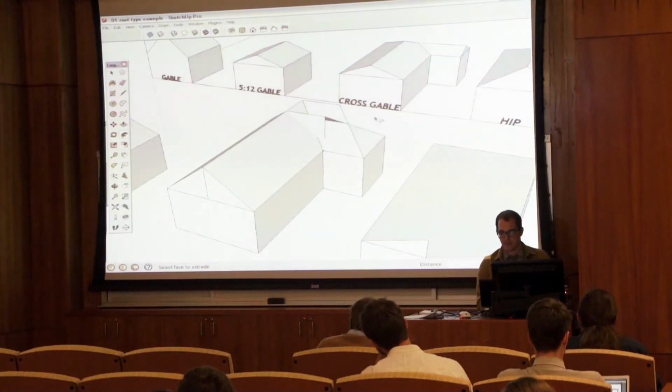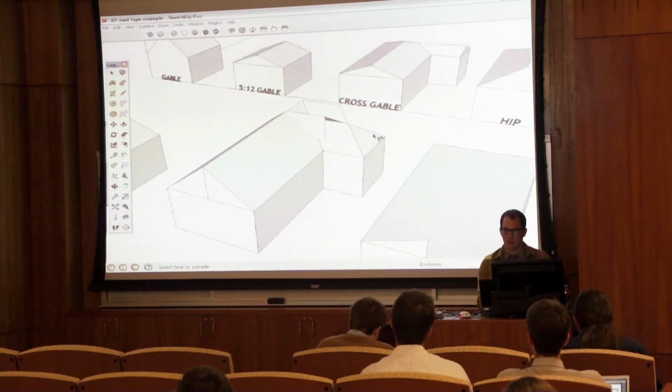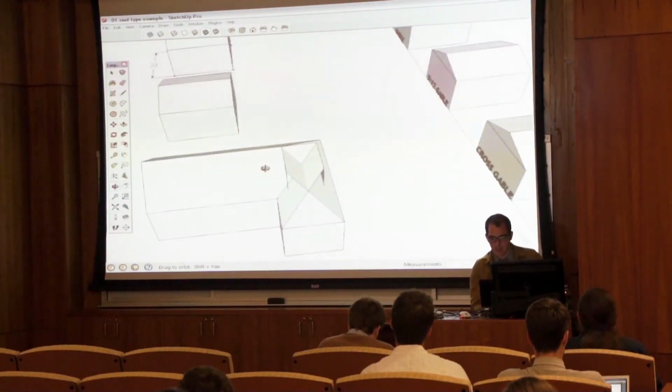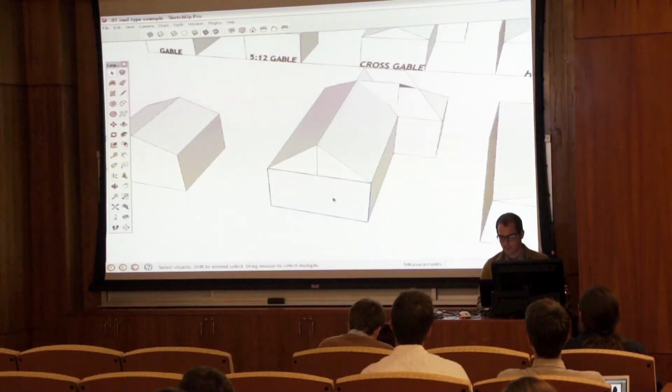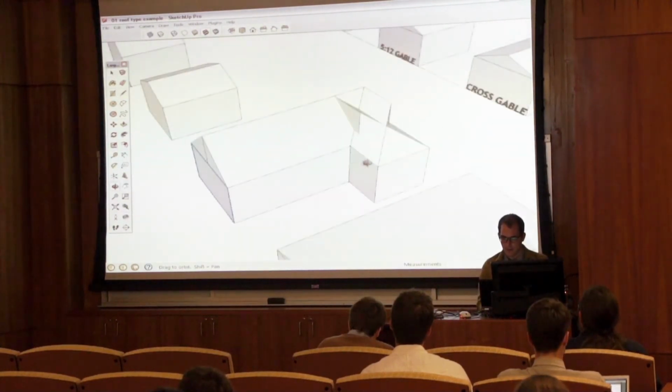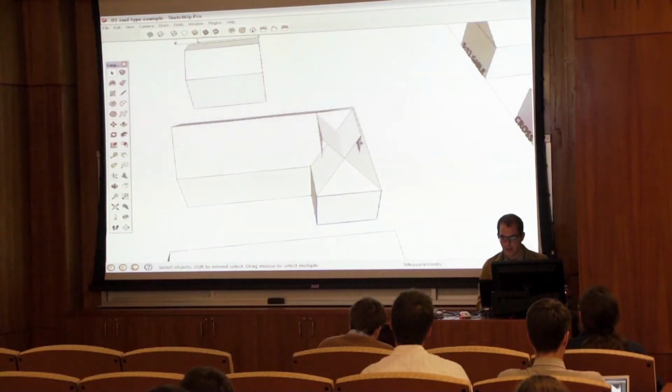Now you'll also notice it creates some additional geometry, and it actually hits that roof there, but we'll go through the steps to actually correct that. The reason why it creates this extra geometry is the width of this is wider than the width here, and that way it creates that geometry. What it doesn't do, however, is intersect the faces for that geometry, so it doesn't intersect this face or line or this line.